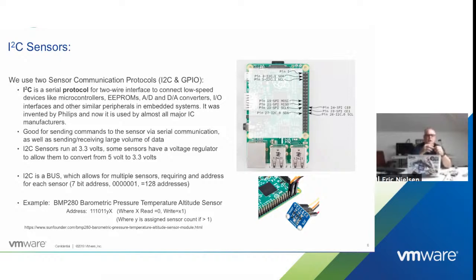Three in one. The point of this sensor is that it has power, ground, but then it has two lines: a clock and a data line. The clock allows the bus protocol to synchronize when it's sending out data and when it expects data to return. So notice an I2C sensor will have more than just 3 pins.